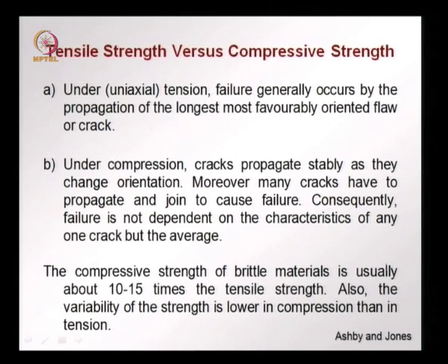Also, when we look at compression, we noted that cracks will propagate in a stable manner and change orientation. You saw the inclined crack becoming vertical at the ends. Many cracks have to propagate and join to cause failure, and consequently the failure is not dependent on the characteristics of any single crack, but on an average. Many cracks contribute, many cracks have to propagate stably and join together.